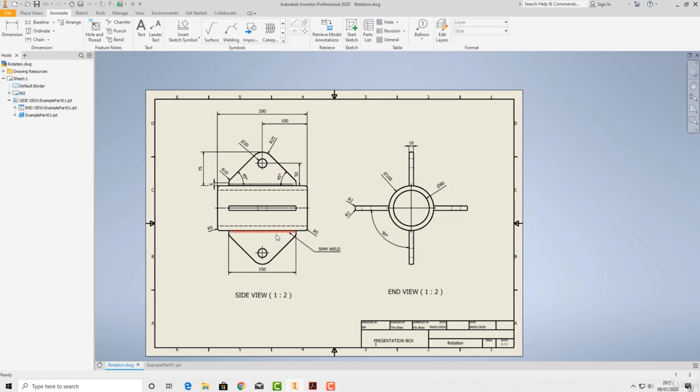You can do the frame generator. If you have something like a frame, maybe like an aeroplane fuselage frame or a racing car frame or something like that, there's a frame generator where all you do is sketch out single lines for the center points and say, right, go and make this with 50 millimeter diameter tubing, and it turns all those lines into tubing. You can also do the fish mouthing and everything, and then spit it out as a cutting list to send to someone to cut out all your tubes, and then your frame can just be welded together.